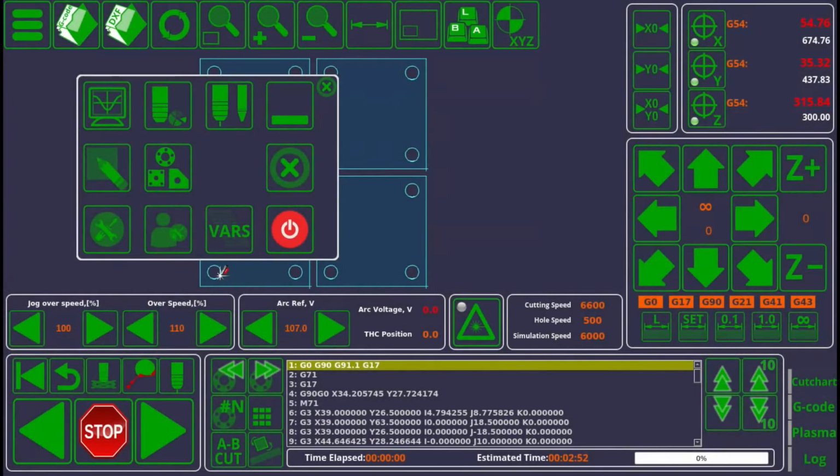So in this video, we'll be taking a look at two sets of codes which exist in myCNC that are designed to turn your torch height control, or THC, system on and off. And these codes would be M14 and M15, as well as the M50 and M51 codes. These are two sets of codes which are designed for a similar task, however they have their separate applications.